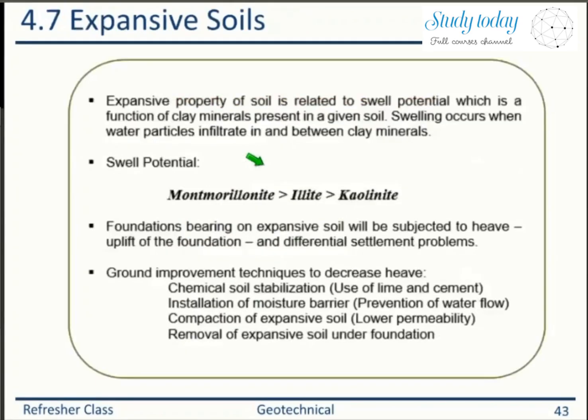Okay, very good. Now, another thing that you need to know is expansive soil. Your fine grained soil, such as clay, is made of different clay minerals. For our engineering importance, there are three types of clay minerals known as montmorillonite, illite, and kaolinite. If these clay minerals are present in your clay and you happen to use this clay as a bearing subgrade for your foundations or for anything, these clay minerals will expand if they come in contact with water.